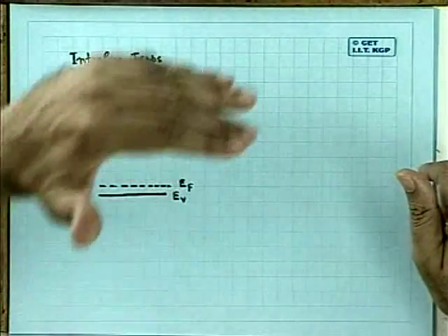But as you come to the interface or the surface, because the lattice is suddenly truncated, what is going to happen? Your Kronig-Penney model, which is based on ideal periodicity, is suddenly hampered. It's called a semi-infinite solid.